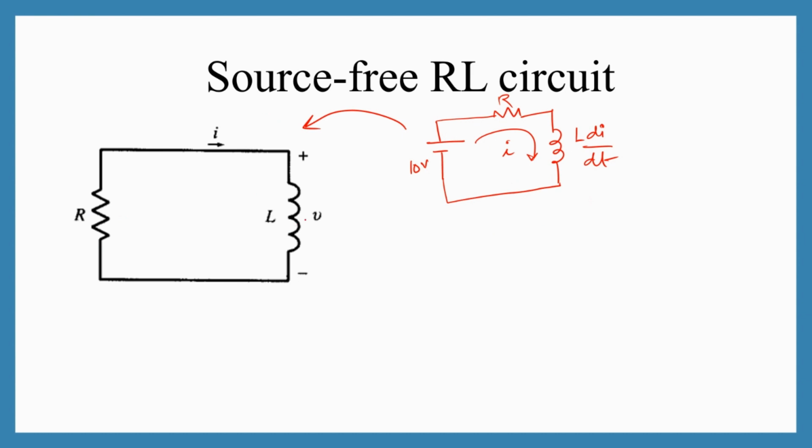So we are going to consider that at t equal to 0, the current flowing through the inductor is I of 0, which is I naught, because it was connected to the source for a long time, and therefore, over a period of time, it got stabilized, and the steady state current turns out to be I naught.